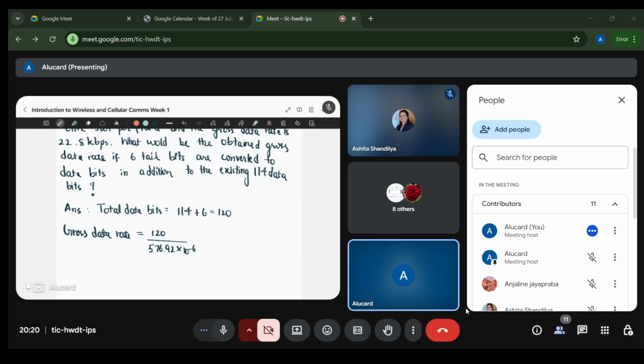But you're only transmitting for 1/8 of the time because there are 8 time slots. And also there were two frames where you are not allowed to transmit your data. So out of 26 frames, you could only use 24 frames.